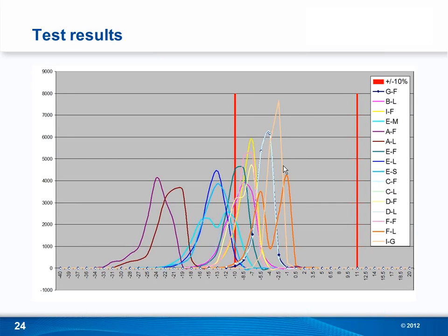And of course, that's the kind of stencil that you would like to see. On the other hand, when you look at the far left side, you see apertures that are way outside the distribution. So the first one has a very desirable high CPK, but the ones that are shifted to the left have low CPK.